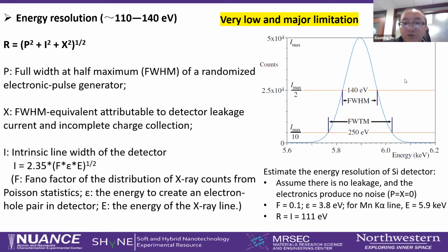Now another thing you want to consider is the spatial resolution of the EDS. The spatial resolution of the EDS is governed by the electron beam and specimen interaction volume. This is a function of the incident beam diameter and the beam spreading.